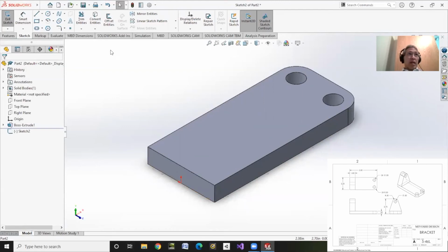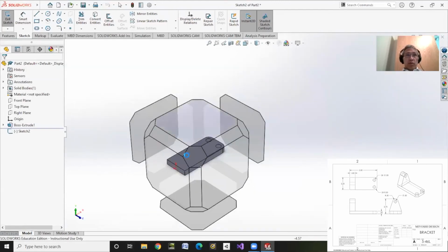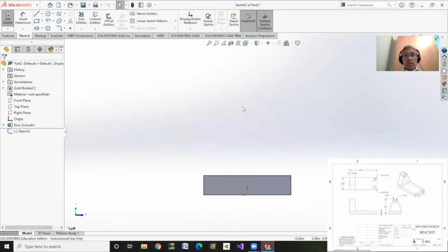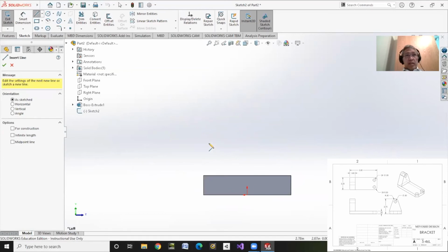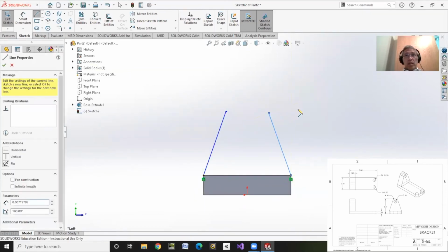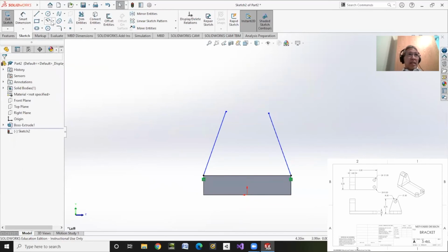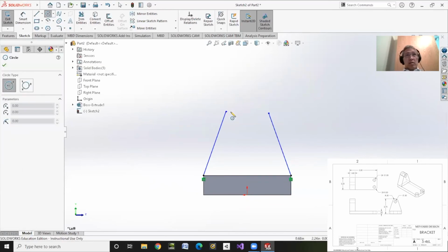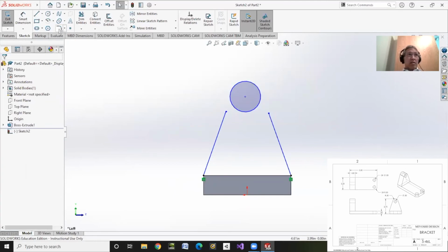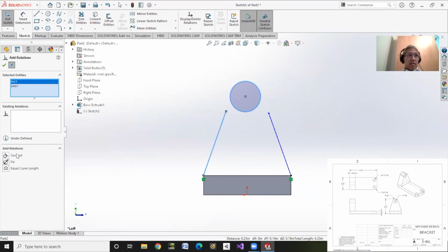All right. So let's go back to the view here, that left view, and all I'm going to do is make a couple lines. I'll make this line here, right click and end of chain, and then I'll click from that endpoint and go here, right click, select. And then, instead of making a fillet, I'm going to make a circle. Now let's make the circle here, select. And then I'll do the same thing I did with the last figure with my tangents, all relations. I'll make this guy and this guy tangent, and this guy and this guy tangent.